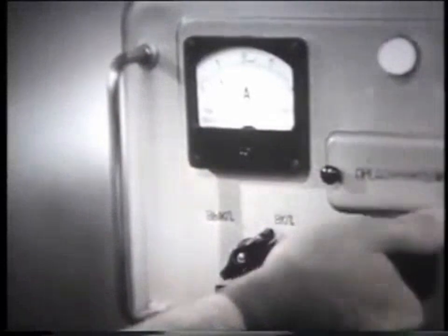It follows from Faraday's law that the rate of metal dissolution is proportional to the current density of the anode. However, with a significant increase in the current density in the non-flowing electrolyte, it is possible to slow down or completely stop the process. What is the reason for this phenomenon?